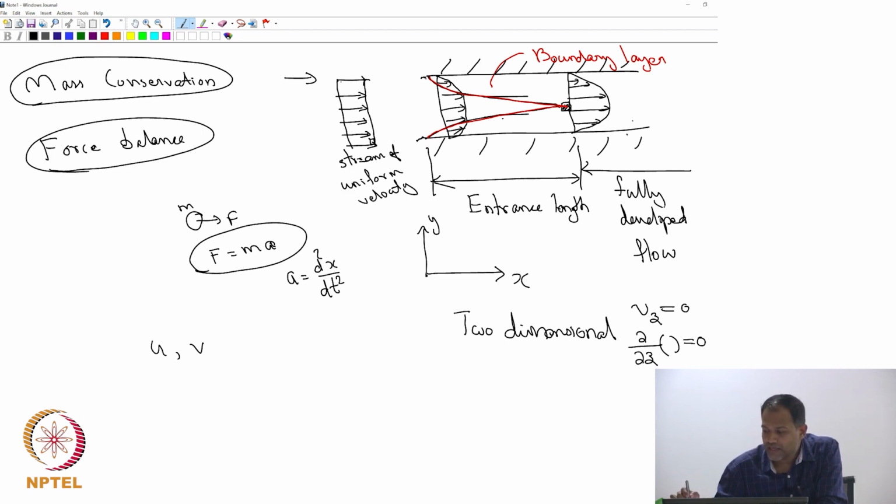So, if the fluid element, let us say fluid element here, the velocity in this direction is what we called as v, and if that is constant everywhere in the domain, then what should that constant be? Why should that be 0? Because there is nothing that can come from the wall to outside. So, any fluid element that you are going to look at on the wall should also have that constant velocity, and we know that that velocity is 0 at this wall, we know that velocity is 0 at that wall. That means there cannot be a velocity that is normal to the walls.